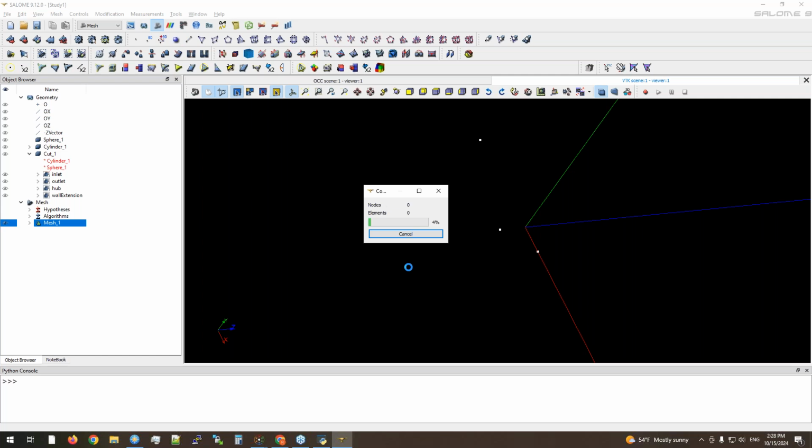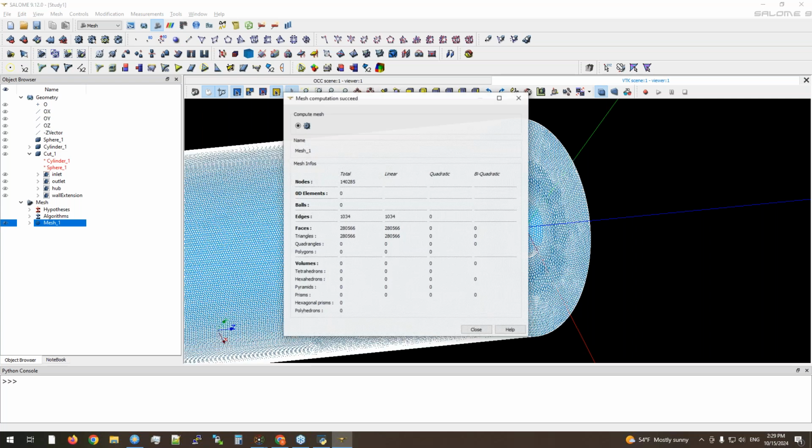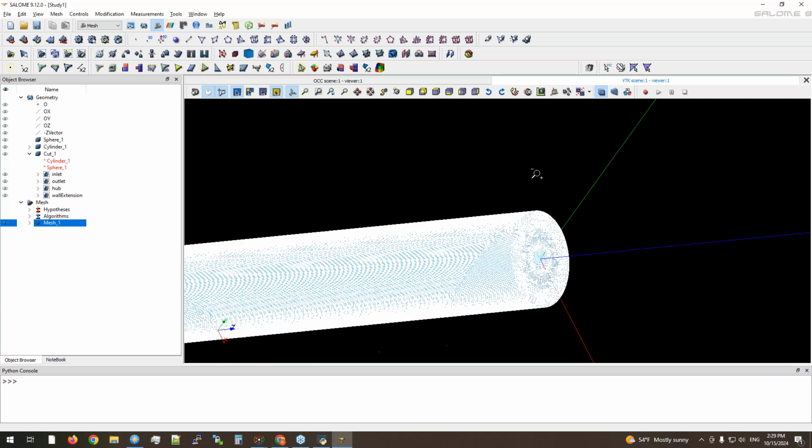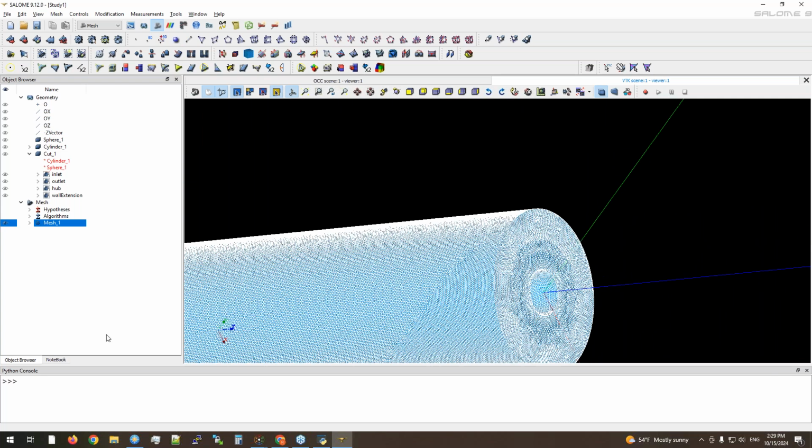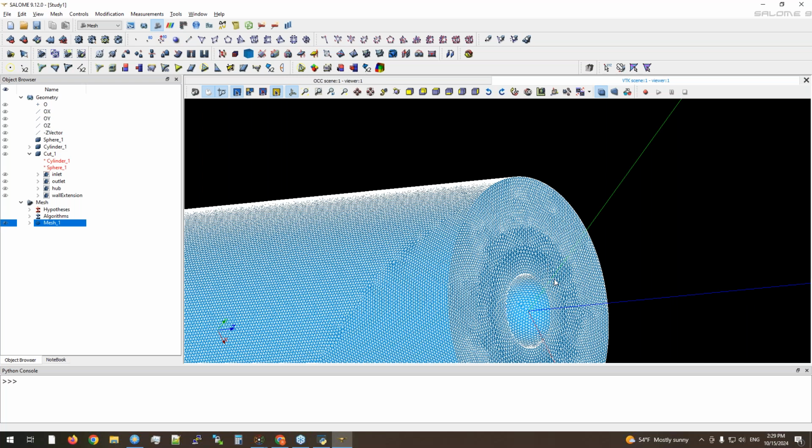Now the meshing is generated, but maybe it will be too fine. But let's keep it. You can also manage local refinement, so you can set finer triangulation on the small and highly curved parts, and rougher triangulation for the bigger and flat parts.